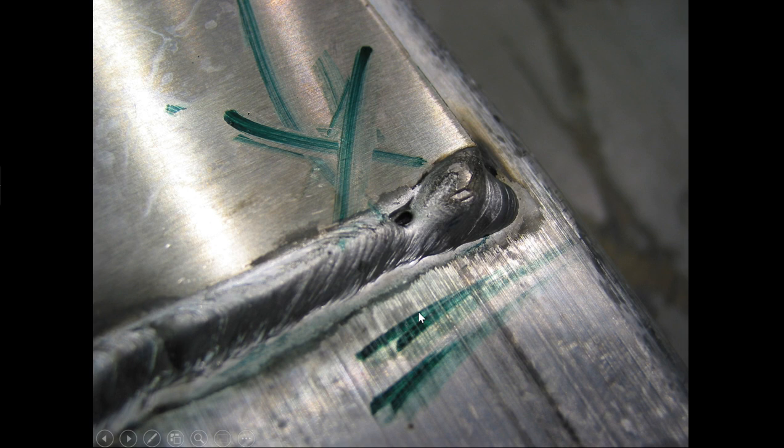And this is something called melt back. You see this often in aluminum, where the material runs away. Now, if you see a lot of melt back, there's a condition that happens inside your welding programs, and we've got to make sure we have good torch angles. There are torch angles to be conditioned, and there's also something called arc blow. Sometimes the robots do this.